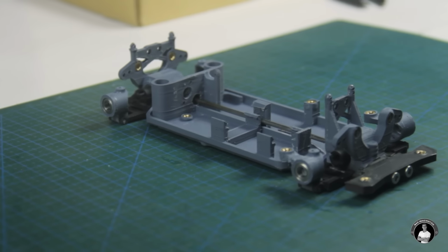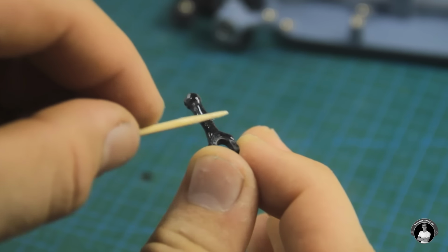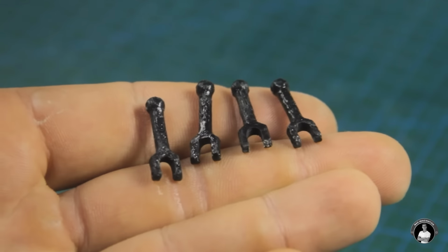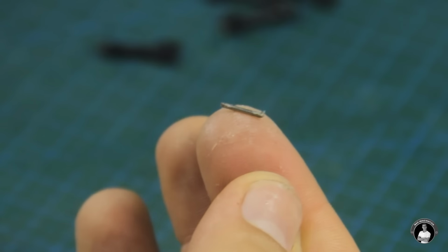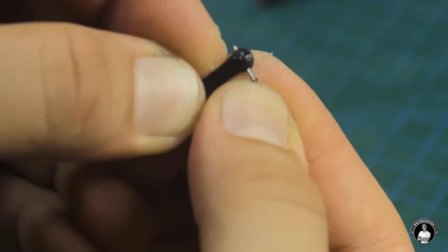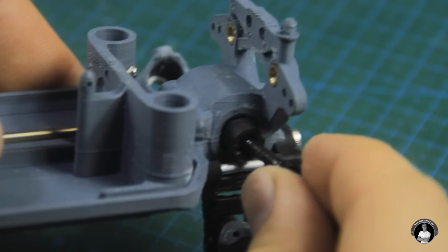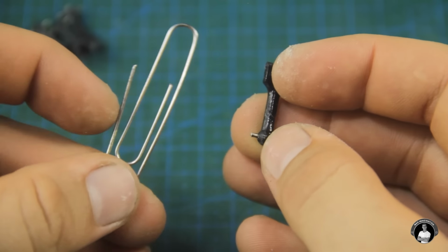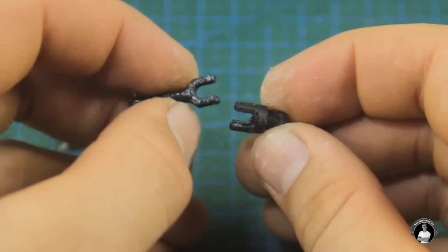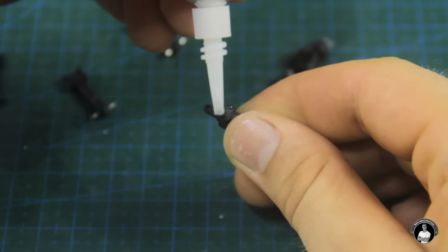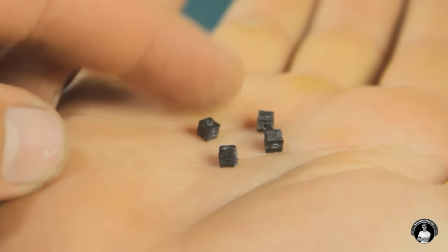For the universal joint drive shafts, if made out of PLA, each one of these dog bone looking pieces needs to be fully coated in superglue to prevent it from breaking when under tension. We can then cut an 8mm section of paperclip wire, which gets pushed into its ball hole for grip. Then with some more paperclip wire, we can adjoin the dog bone piece with the wheel connecting part of the joint through one of these little cubes.